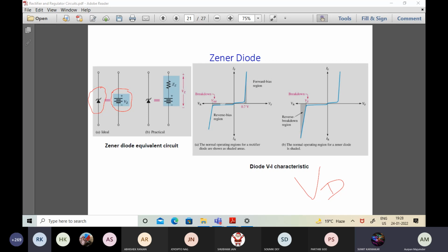That's a separate story. But this quantum mechanical tunneling of electrons is far more effective in the process of current generation in the reverse bias context. And that phenomenon is very different from the carriers bypassing the barrier and getting into the other half of the junction, as happens for the majority carriers in the forward biased operation of the diode.